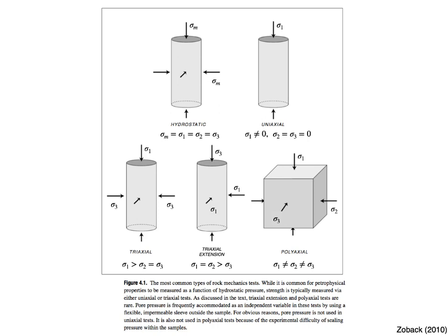Finally, on a rock cube, we can apply different stresses to the faces of the cube. This test is called polyaxial or true triaxial. The uniaxial and triaxial tests are the most common. The polyaxial test, because of its complexity, is rare.